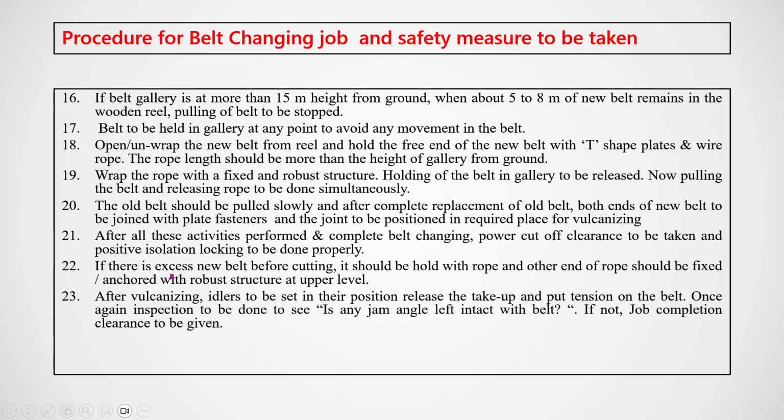If there is excess new belt before cutting, it should be held with rope, and the other end of the rope should be fixed and anchored to a robust structure at the upper level. After vulcanizing, the idlers are to be set in their positions, then release the take-up.